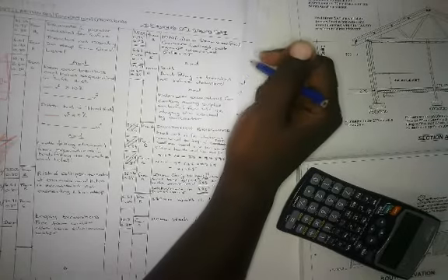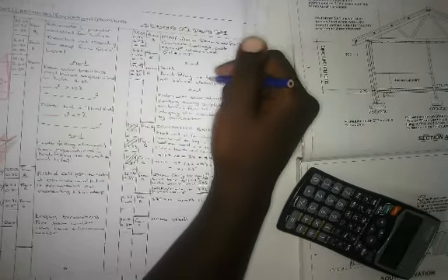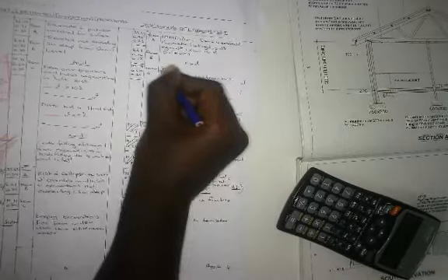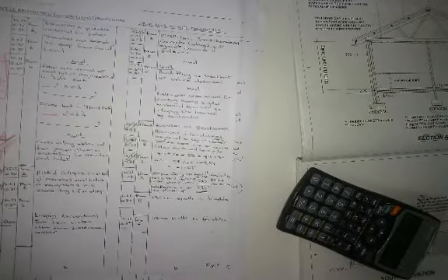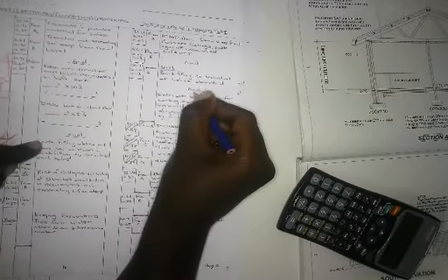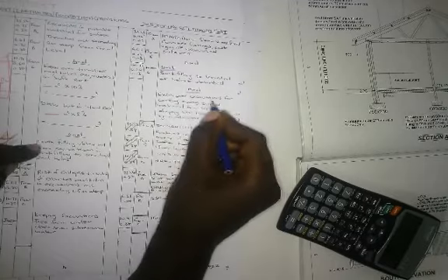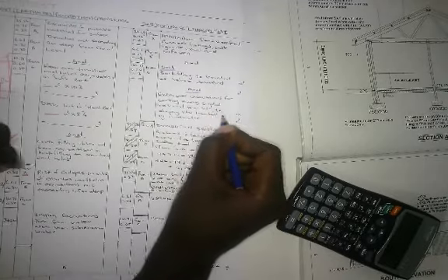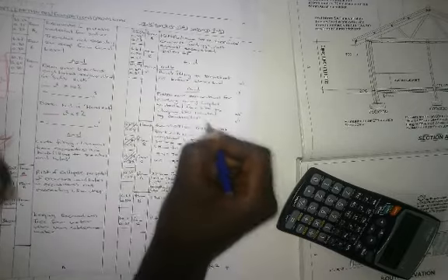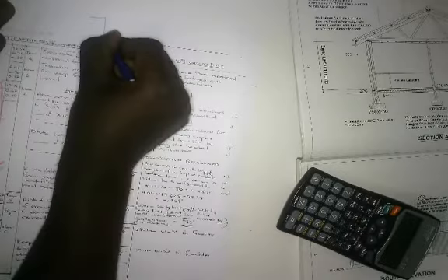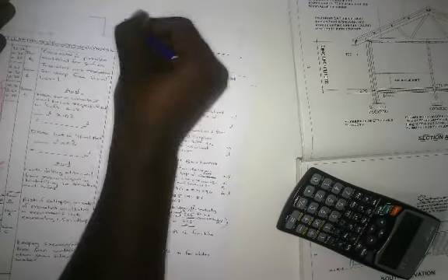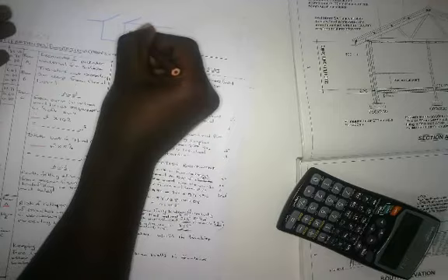Okay, now let me read that concrete so that you can understand the backfilling part that I spoke about. So when we come to our footing, we say 10 MPa 19 mil stone unreinforced concrete cast against excavated surfaces, and then we say and deduct. We're going to deduct now backfilling to trenches and holes as described before. And then we're going to say and extra over excavations for cutting away surplus material from site to dumping site selected by contractor. What do we mean by this?